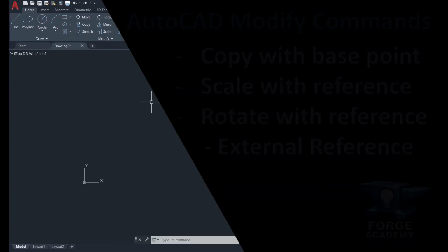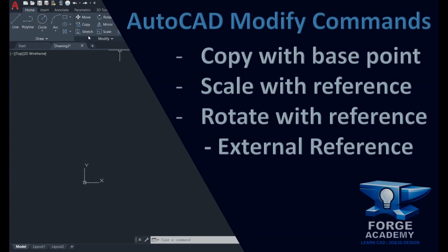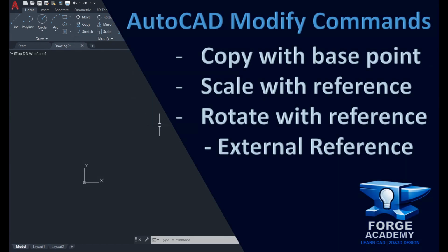Today we are going through the second part of modify panels and the reference feature from scale, rotate and also copy with a base point. We have already learned how to use the basic modify commands in the other tutorial, so watch that one first.